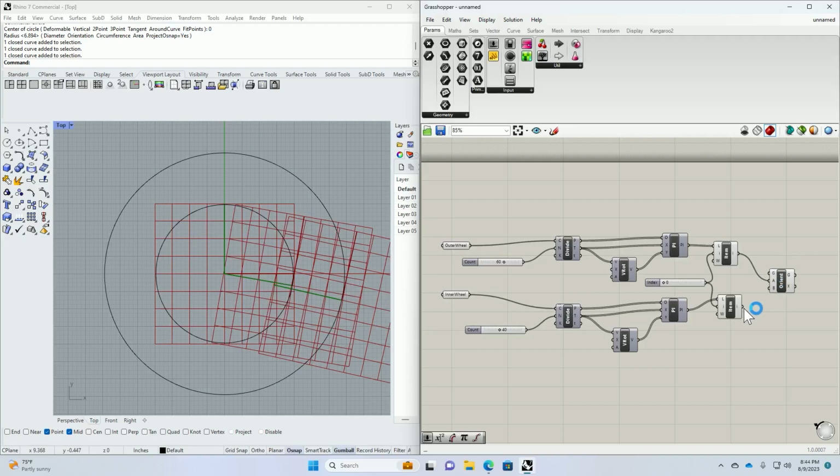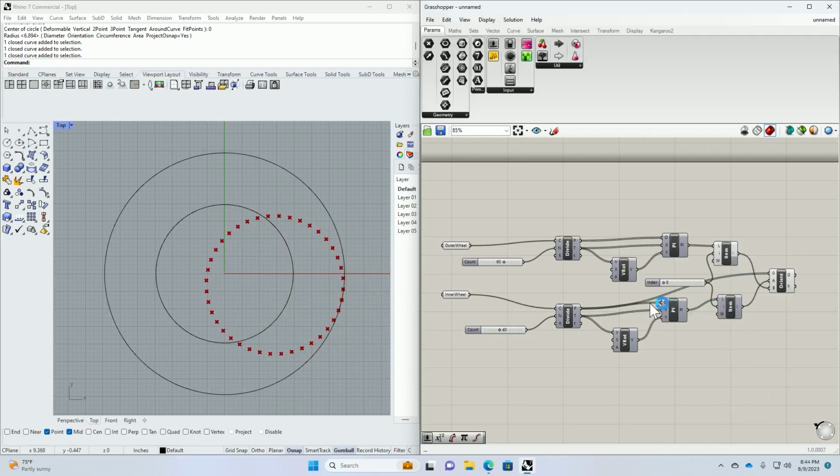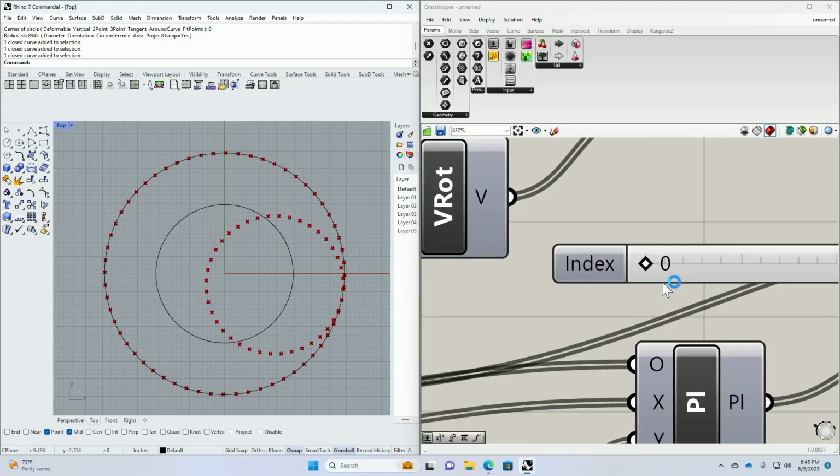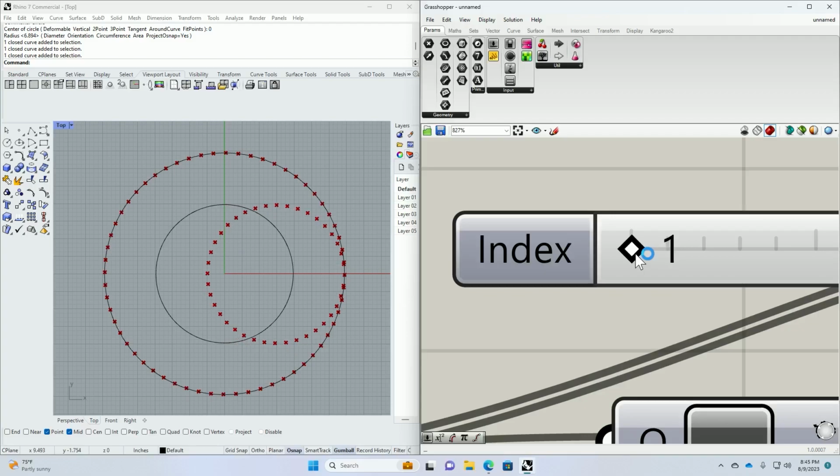So actually the inner wheel is the start plane and the outer wheel is the end plane. And so that we can actually see things moving, we'll move this geometry, but we'll also move these points. We don't need to see those planes. So you can see how it's already reoriented this curve from 1 point on, and I guess we'll make these visible so that it aligns on that. And then if we go to the next one, you can see how it just rolls along, just as if those were gears.